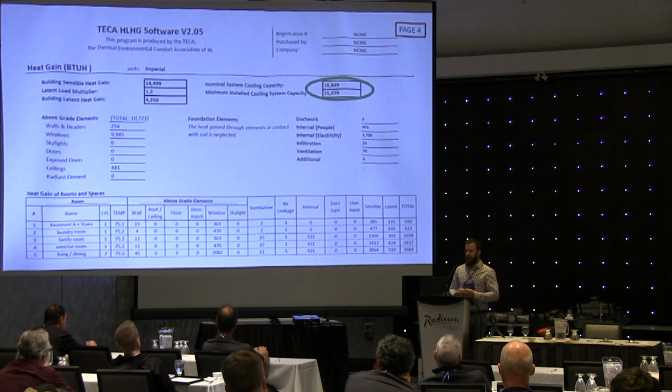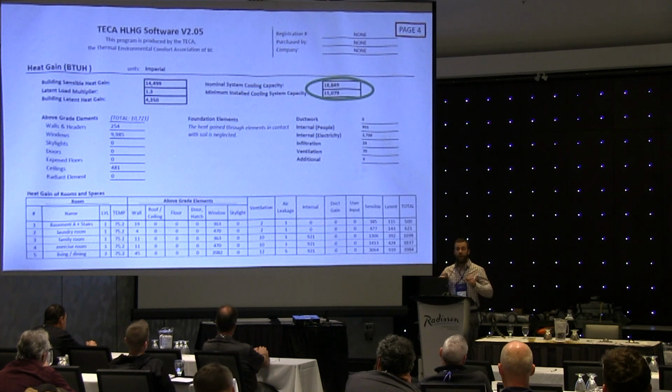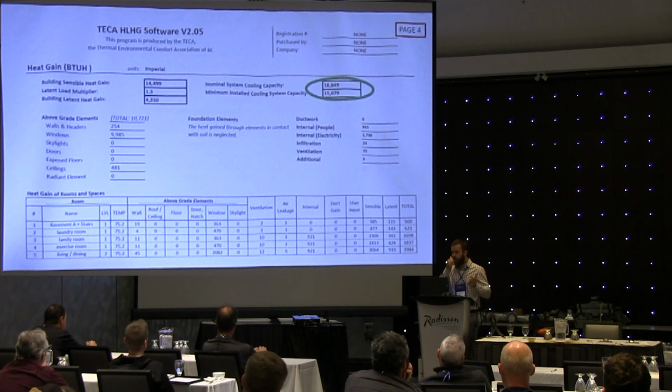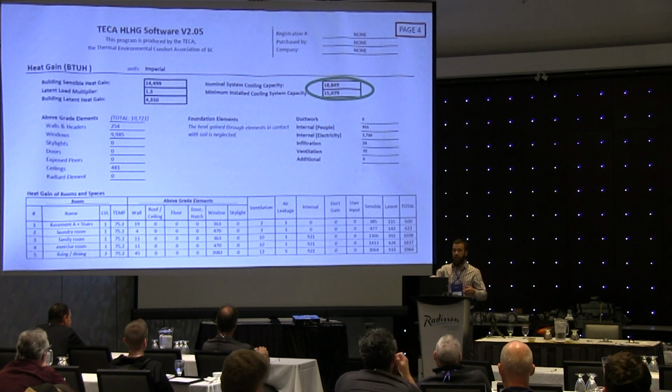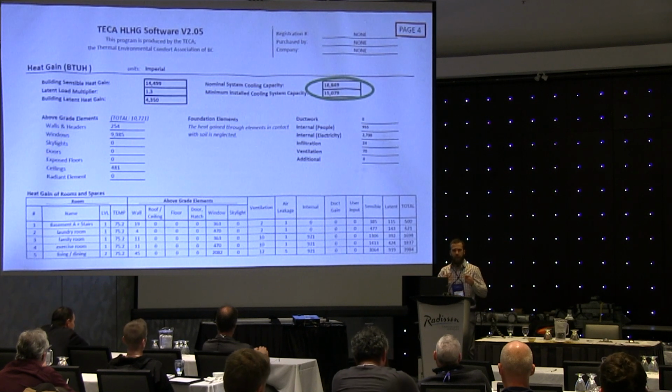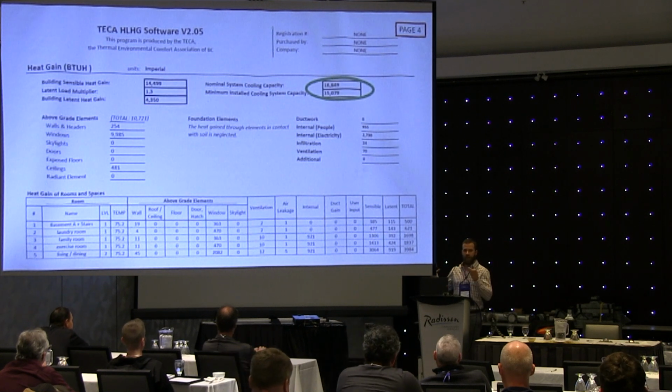So it's when we have things in the building that produce extra heat that you also have to cool. If I have a kitchen, building a house with a kitchen, that kitchen might have the stove operating, might have everybody sitting around the island and talking. So all these people, all these appliances are going to be producing heat. I still need to cool that room appropriately, so I need to consider those loads as well.